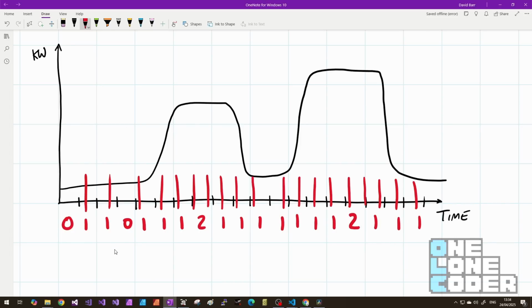The blinking LED is reasonably low frequency, so most of the time we might actually not count anything at all. This means we get these bursts of counts that we do see as it's catching up. Worse still, we're basically throwing out resolution. We can't discern any difference between whatever this device is and whatever this device is. Yes, on a macro scale we can, but really I'd like to know precisely what the wattage is being consumed by my house at any given time. We need to think differently about how we interpret what the blinking LED means.